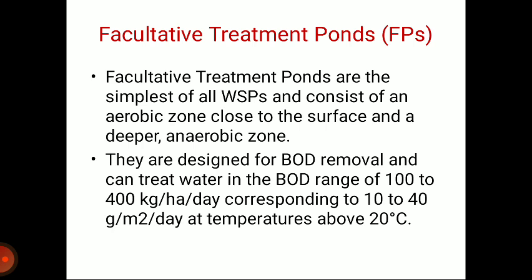Facultative treatment ponds. Facultative treatment ponds are the simplest of all WSPs, and they consist of an aerobic zone close to the surface and a deeper anaerobic zone. They are designed for BOD removal and can treat water in the BOD range of 100 to 400 kg per hectare per day, corresponding to 10 to 40 grams per square meter per day at a temperature above 20 degrees